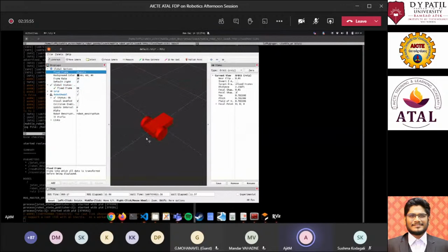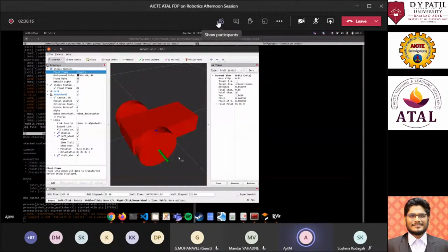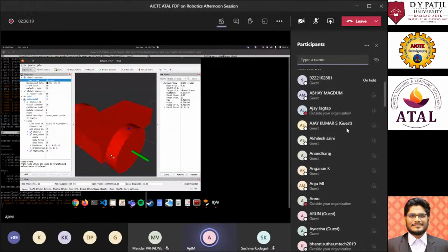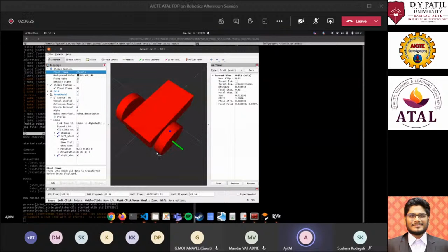Yeah, so this is again the rotated wheel, and we go back to the left wheel, and when we show its axis, you can see the y-axis coming out of here. Remember the red one was x, which is in this direction. You can see it protruding a bit over here. This small thing is X, this is Y, and this is Z. So the rotation will be along the Y axis for this wheel.